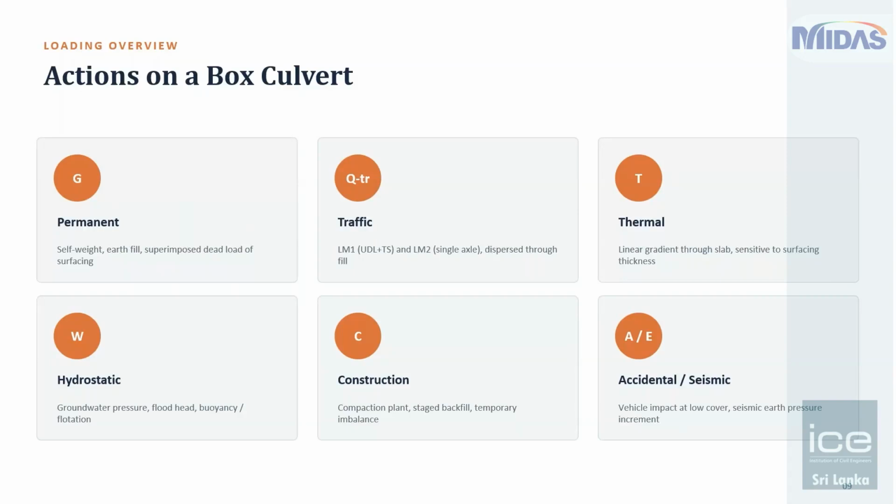Okay, now there is something called scour depth as well. So generally in hydraulic designs, we would consider the base slab to be resting below the scour depth, or we would improve the soil so much so that the scouring is controlled, or the scour depth must not fall below the level of the bottom slab base. Okay, because if you are getting a scour at the base of the box culvert, then your soil will get removed and basically your box culvert will no longer be stable. So we need to control for that scour depth, right?